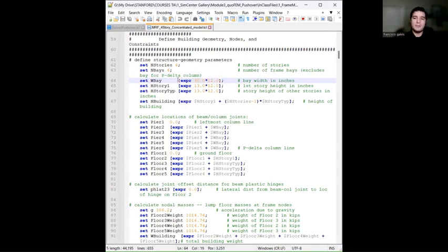And every time you define a value in Tcl language, you do a multiplication or a division or any kind of parameter or float operation, you need to do it this way, with brackets and putting the expr symbol behind. So that's what we're doing.